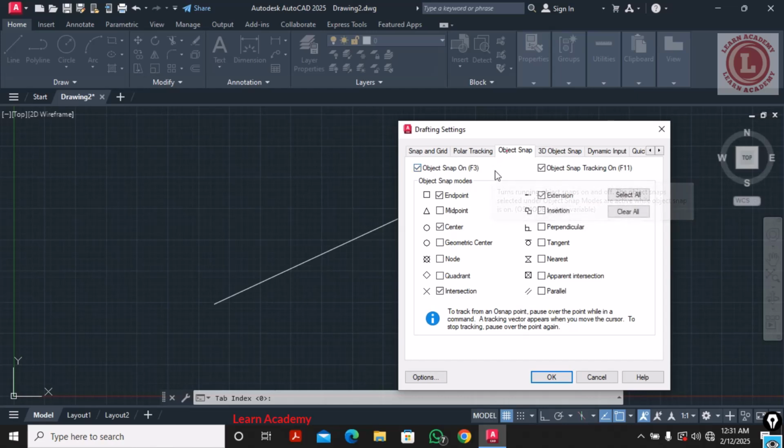The reason why you need to set your object snap modes is because when we are drawing, sometimes we want to pick certain points, or place an object on a certain point that might be difficult to position. So the object snaps, if they are activated, help AutoCAD to display those points when my cursor is moving over that particular object.